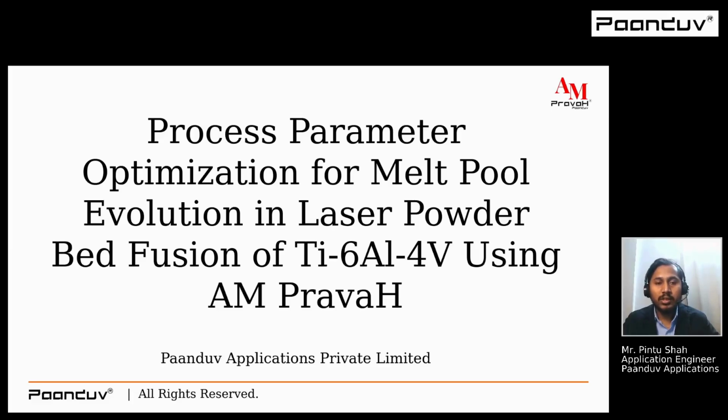Today I am going to demonstrate our software AM PravaH, where we have exactly matched the experimental result with the simulation result. Today's topic is process parameter optimization for melt pool evaluation in laser powder bed fusion of Ti-64 using AM PravaH. AM PravaH is additive manufacturing software, and it has a four-phase multi-phase system, so it covers solid, liquid, gas, and vapor.